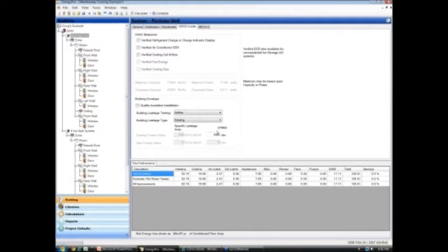When you do your blower door test, you get a CFM 50 result. You enter that result right here. So that is your CFM 50, cubic feet per minute at 50 Pascal. That's when you're doing your blower door test. Bingo, you put in that result right there.